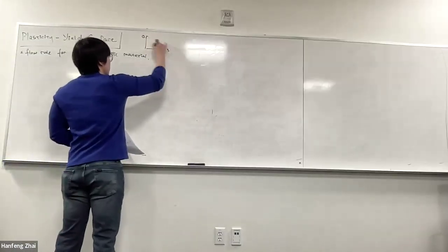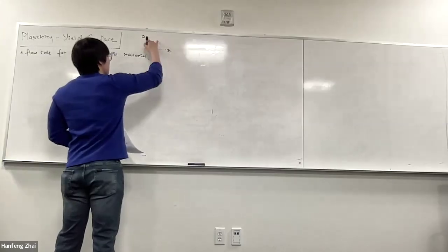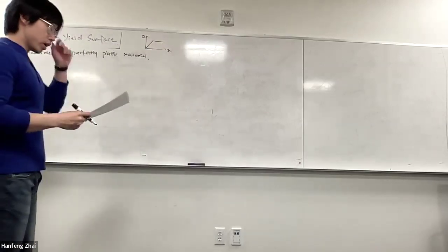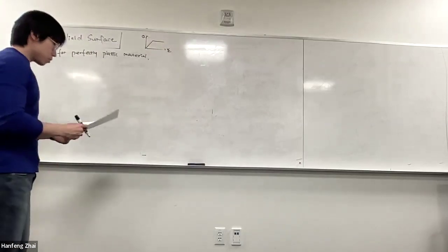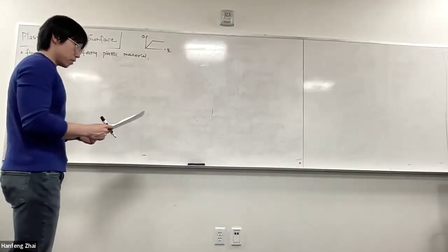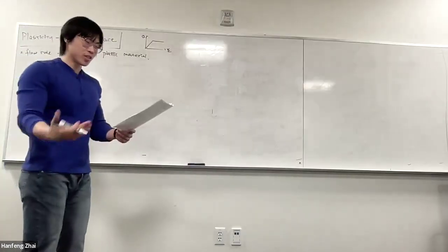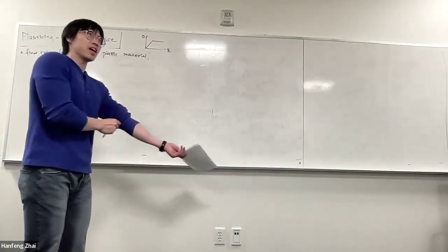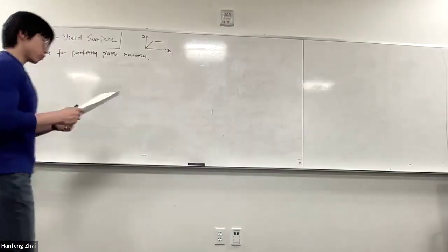Stress and strain. Once you reach the yield point, the stress remains the same. There's no strain hardening or strain softening. And also, I would assume you already know the basic equation of plasticity, at least from lecture note chapter or handout number 13. Now I'm doing 14, right?